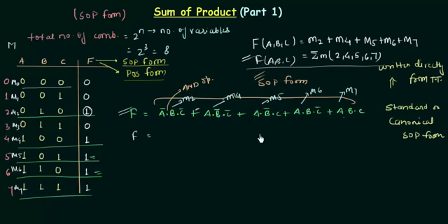So let's do it. In the last two terms, you can see AB is the same, and in these two terms you can see AB complement is the same. So I can write it like A complement B C complement, or AB complement is taken as common from the distributive law, and we are left with C complement or C. From here I have AB, and in bracket I have C complement or C. Now you already know C complement or C is equal to 1.